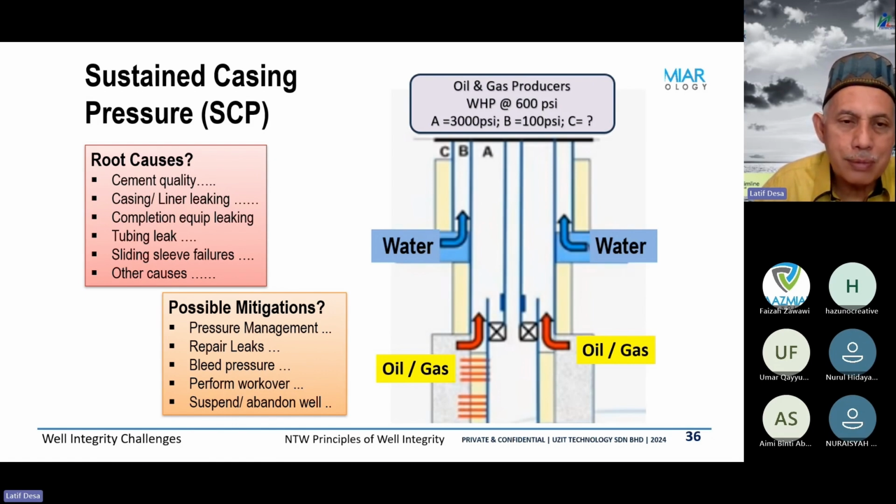If you don't put a check valve, then of course you have to really monitor the well almost every day to see the pattern of pressure increase due to production or due to shutdown and some other reason.